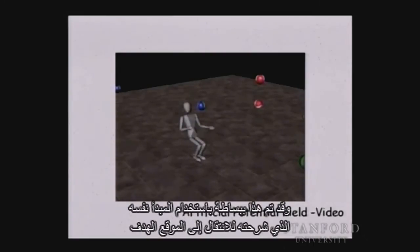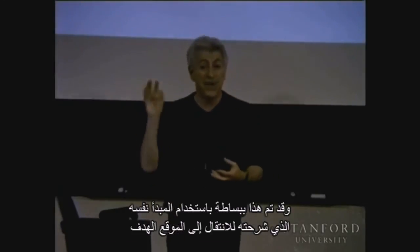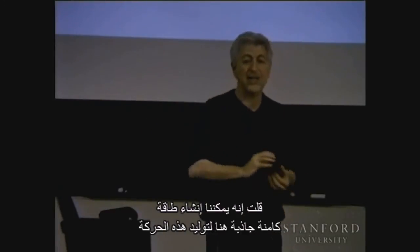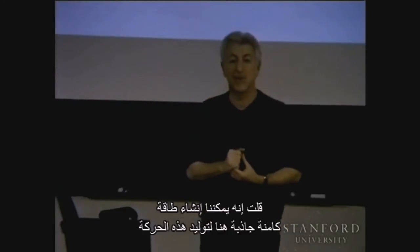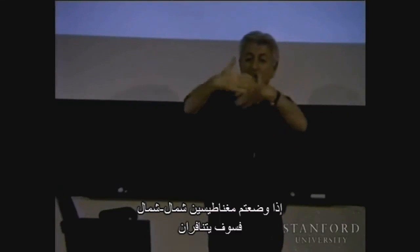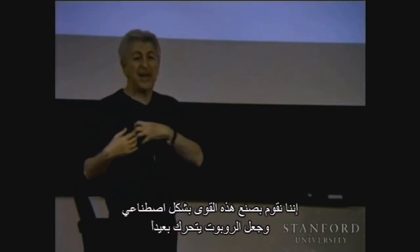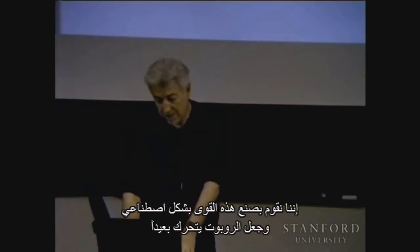And this is simply done by using the same type of concept that I described for moving to a goal position. I said we can create an attractive potential energy. Here, to create this motion, we are creating a repulsive potential energy. So if you put two magnets north-north, they will repel, and this is exactly what is happening. We are creating artificially those forces and making the robot move away.